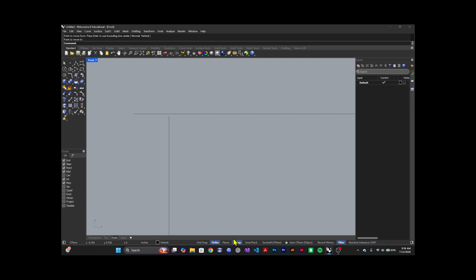I'm gonna turn it on, and then we're gonna hold shift, and then move it. So I take move, and it's gonna snap to the end point, as you guys can see right there. And now I can move it exactly to this point, which is the end. Now it doesn't matter how much I zoom in, I'm not gonna see any gap or anything because the points are connected.